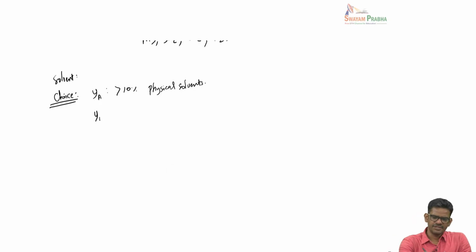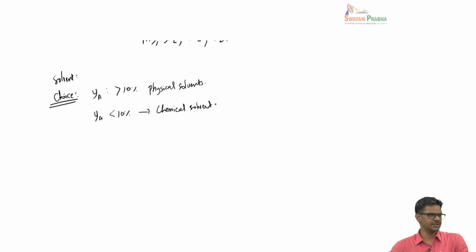When this mole fraction is very small, we would like to use chemical solvents, where the absorption will also involve a reaction between the solute and the solvent.